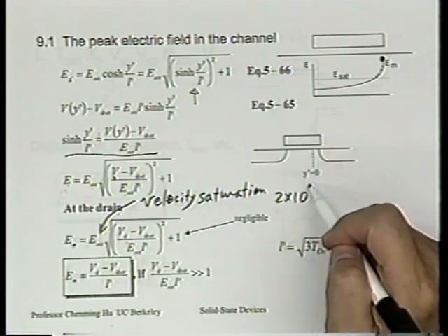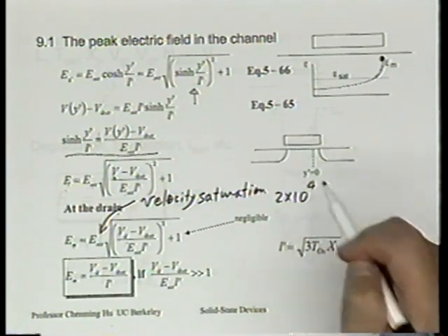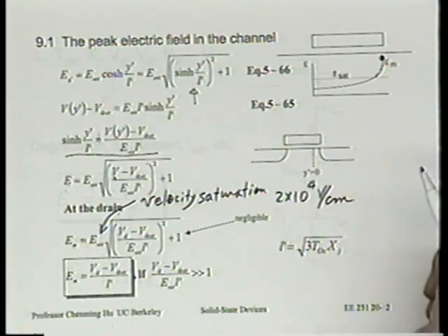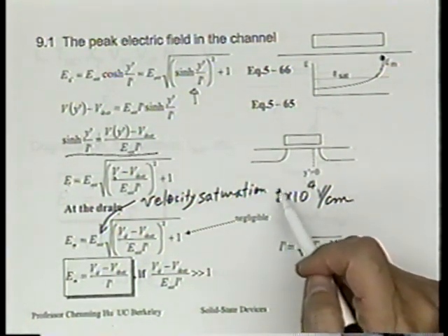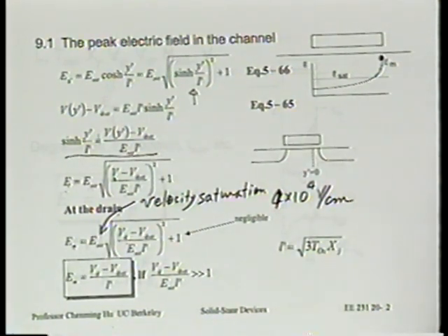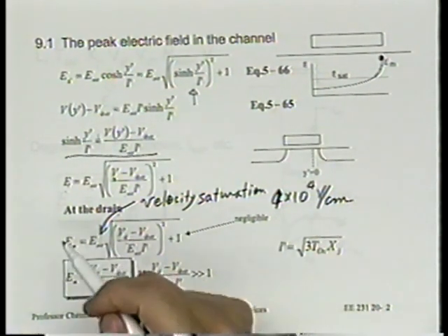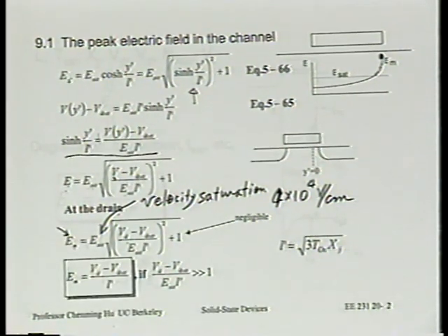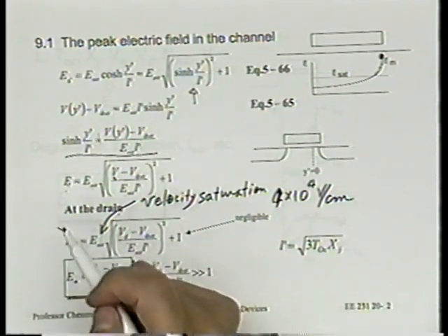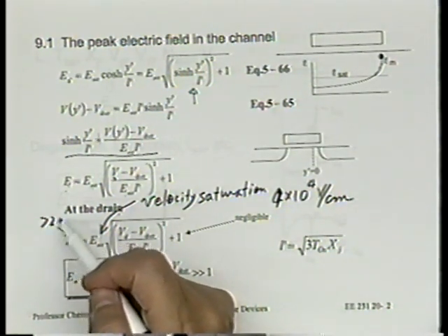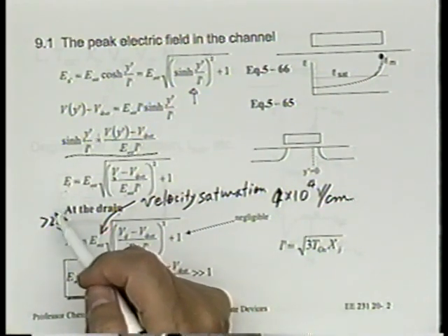So I was really particularly looking for this exponent, right? If you remember it's volt per centimeter, then you're in the right ballpark. I probably would have called it 3 or 4. All right. 4 times 10 to the 4 volt per centimeter. That will be in the right ballpark. Later you will see that all the problems due to high field effect start becoming important when we are at larger than 2 times 10 to the 5, maybe more than that, maybe 4 times 10 to the 5.